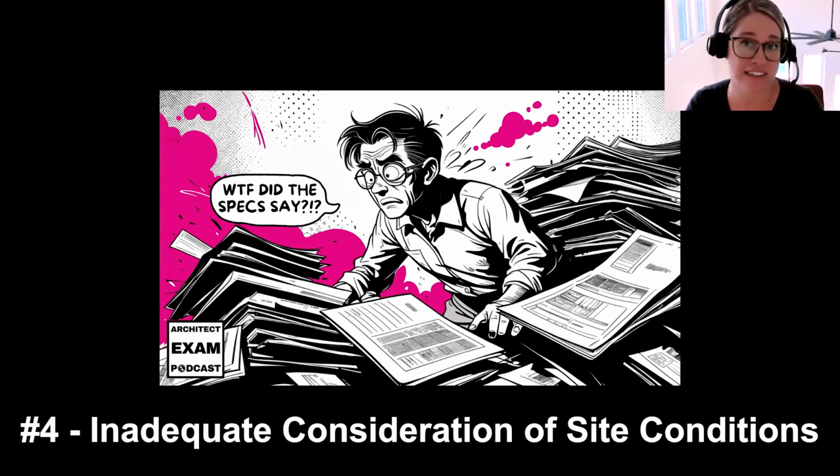And I definitely learned this lesson the hard way working on a project here in St. Thomas in the Virgin Islands. I vaguely specified steel railings on a project only to have them installed and show signs of corrosion very early on after installation, where I realized I should have specifically specified something that would have held up in this environment.